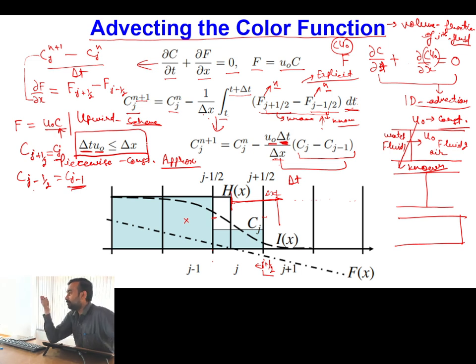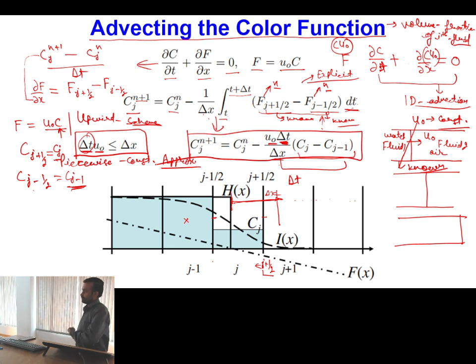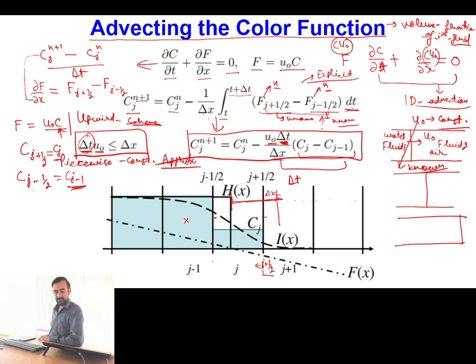Okay, and the combination of the volume fraction time step and the momentum time step, whichever is smallest, that one we use for the numerical scheme. Is this one clear? Now, if I know the value of delta t, that I have to keep less than this criteria, then I can actually obtain this particular equation. Is this one clear?